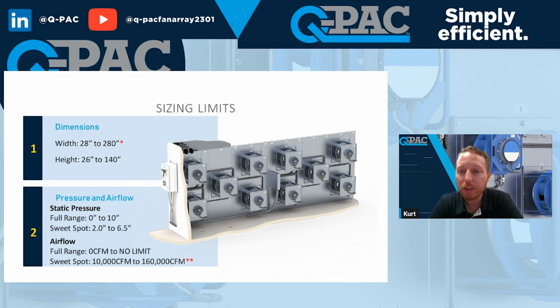Pressure and airflow. So static pressure. I'm showing what we call our full range, which is what we're capable of doing. And then I'm showing what our sweet spot is. Sweet spot meaning where we add the most value. I'll talk a little bit more about that depending on if it's static or airflow. So for static, we can do 0 to 10 inches. We have the capability, we have the fans to do it. Sweet spot, we provide the best ROI between 2 inches and 6.5 inches. That's where you'll gain the most value when selecting a static pressure range.